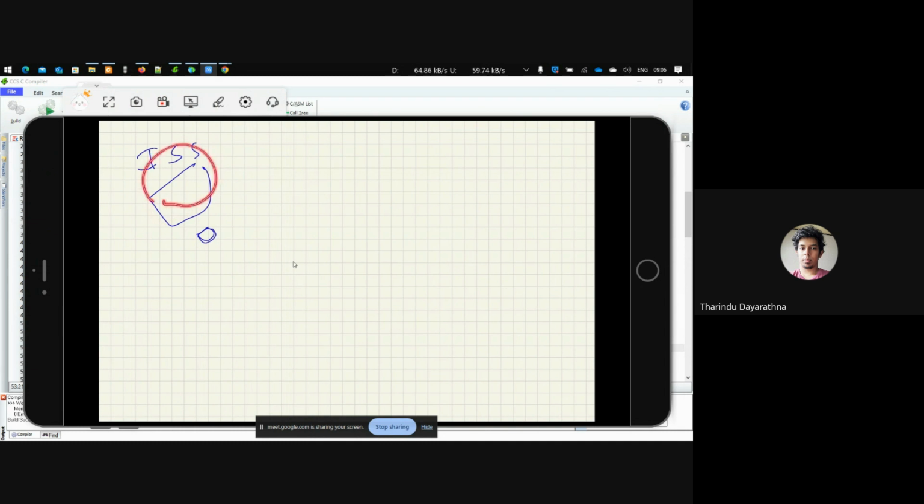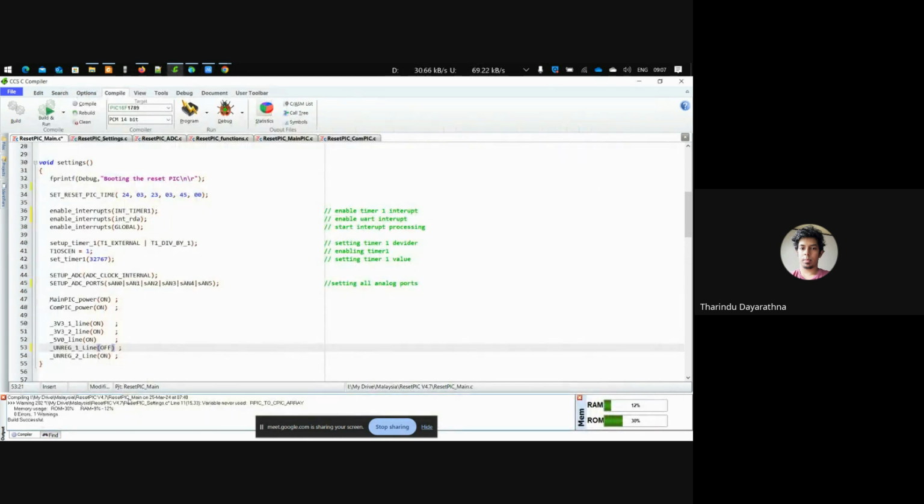So we have ISS. When we release the satellite, ISS has a requirement saying until 30 minutes finish from deployment, please don't transmit any signal. So you have to wait 30 minutes to turn on the transceiver. Which means when the satellite is deployed, the transceiver should be off. So that's why I have to turn off the RF line.